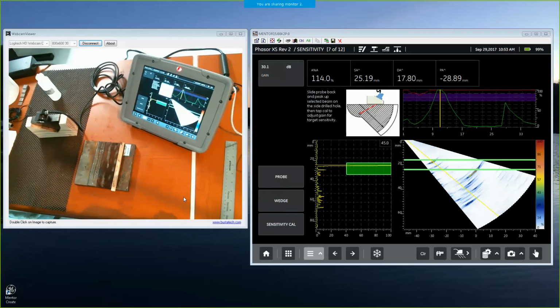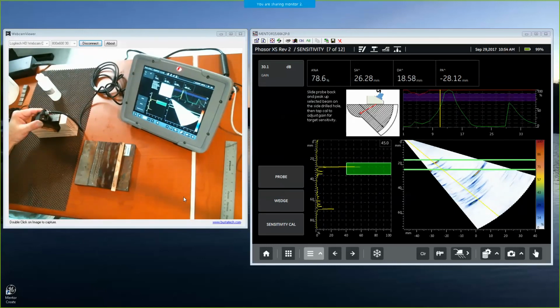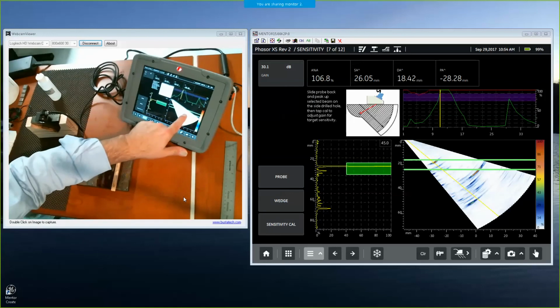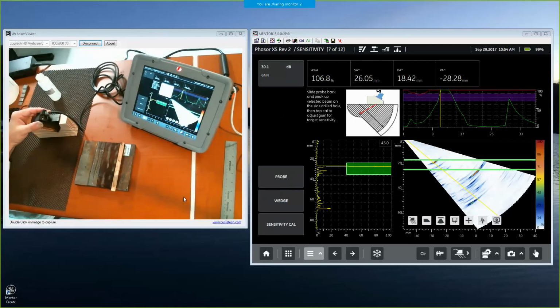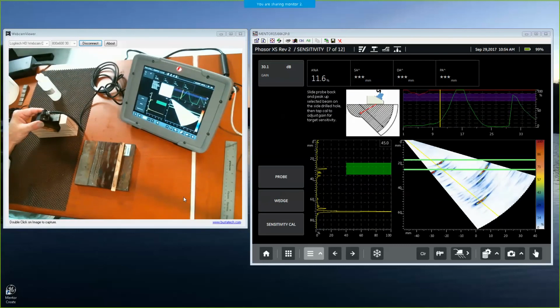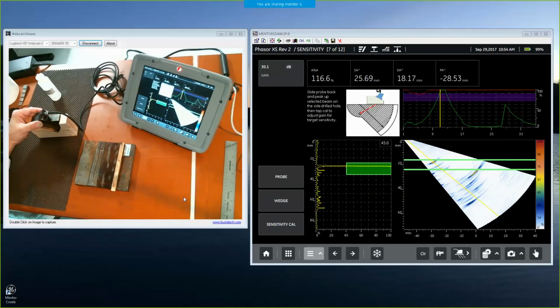Okay. Yeah, either that or you need a physically very large block where you can separate the indications far enough that you're only seeing one indication on the whole sweep of angles at a time. Because right now I'm looking at that side drilled hole on the 45-degree beam. But you notice my shallower beams are already picking up some geometry indication that's up in the gate. And you notice I'm getting an indication on those from that as big as the primary indicator I'm interested in. So this was the most useful approach for this block, put it that way. I just want to get that in before I leave. I've got to drop off here, so thanks, guys.